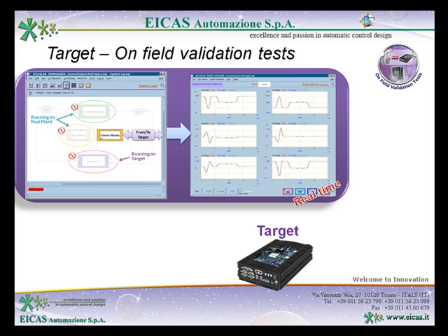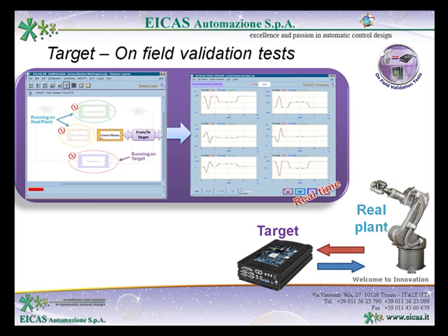the application software, typically related to the control area and possibly to the control mission area, already tested in the two previous modes, and the target basic software generated in this sub-mode, able to schedule in real time the target activities and to manage the input-output interfaces to enable the connection of the target with the real plant. After this operation, you can execute your experimental campaign.